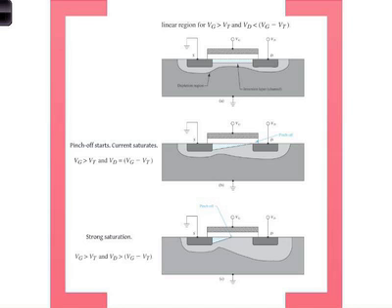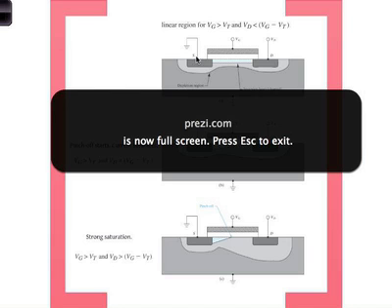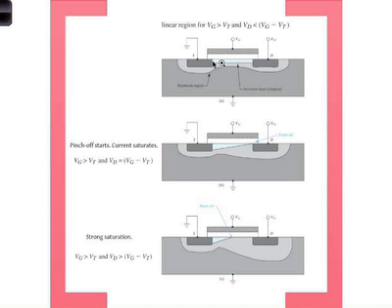Okay? Now it's very simple to understand. Now what you have is essentially you have a voltage between the drain and the source, and you have a channel which can conduct electricity. Electrons. That's it. Right? That's why it's a linear regime. You apply voltage, current flows. It's almost like a resistor. A straight line, current voltage curve. Okay? Now the threshold comes up because you need to have sufficient number of electrons here for the channel to happen, which means you have some minimum voltage that you need to apply. That's the threshold. That's the physical meaning of the threshold. Okay?